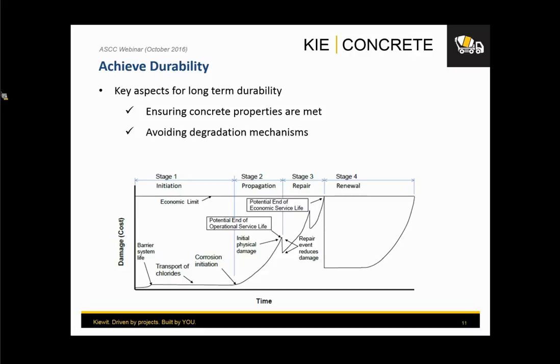Then avoid degradation mechanisms. And here we're talking about degradation mechanisms such as the freeze-thaw issues, right? Or the corrosion of the rebar, or the scaling of the surfaces, right? We're talking about things that are going to affect that concrete performance in service, that are going to create distress in the concrete, cause cracking with time, right? And are not going to allow the material to perform right in the long term, right?